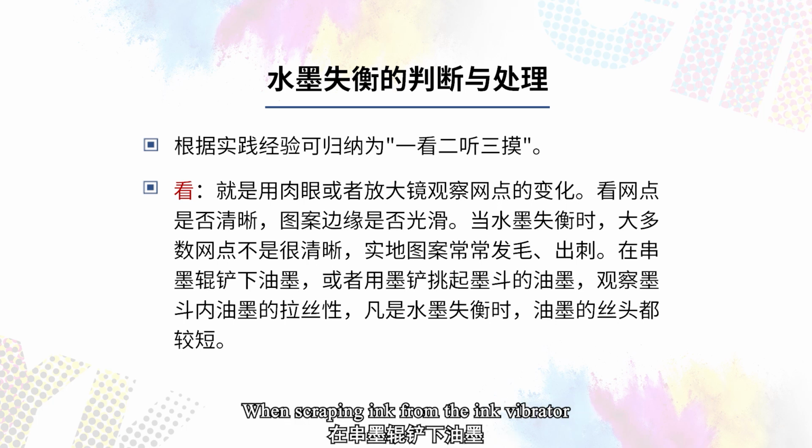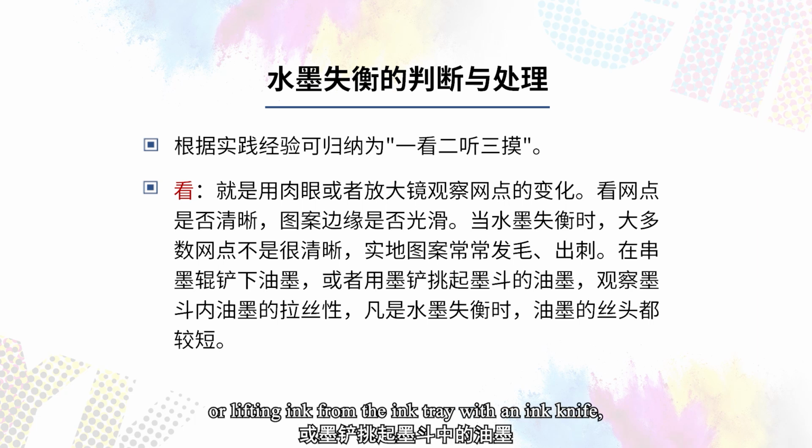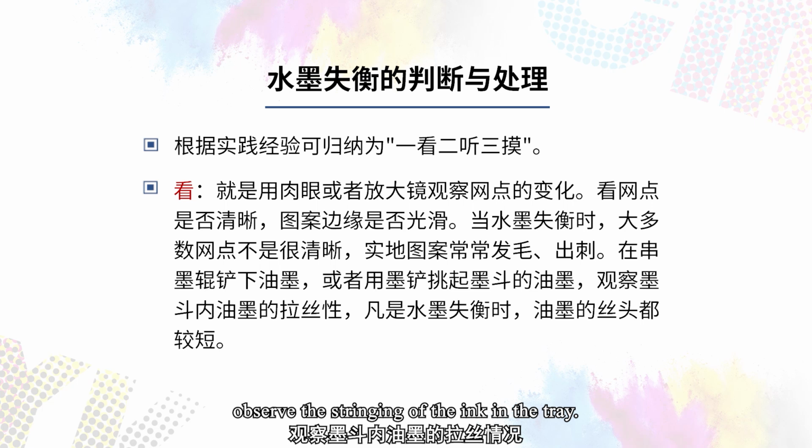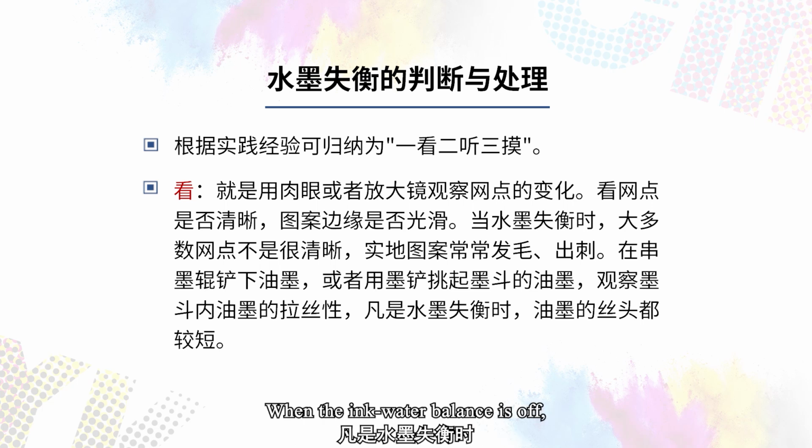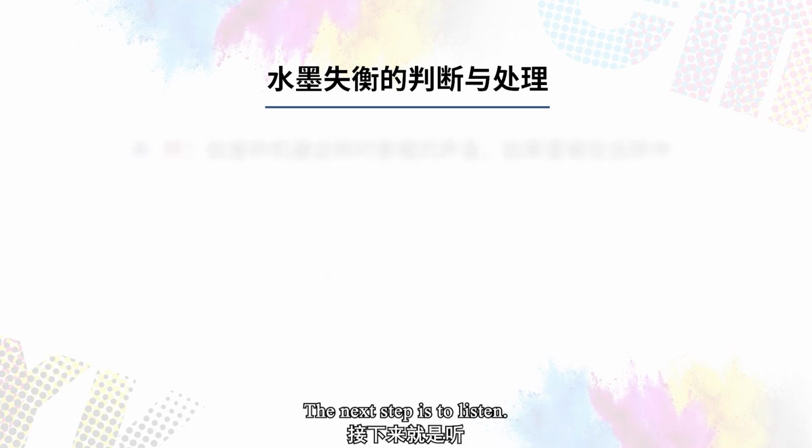When scraping ink from the ink vibrator, or lifting ink from the ink tray with an ink knife, observe the stringing of the ink in the tray. When the ink-water balance is off, the filament of the ink is often short. The next step is to listen.